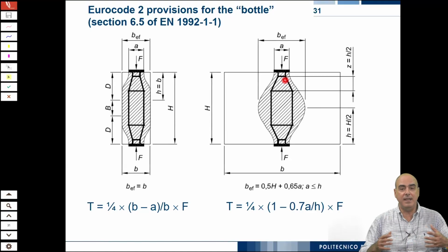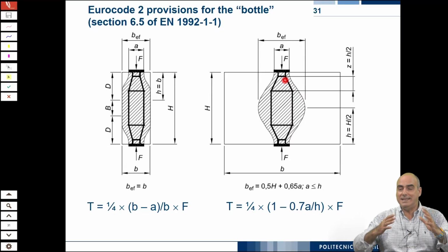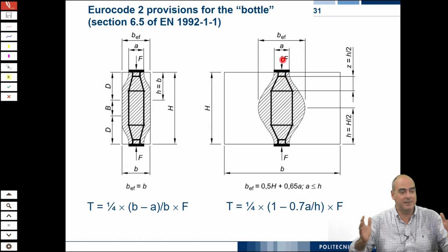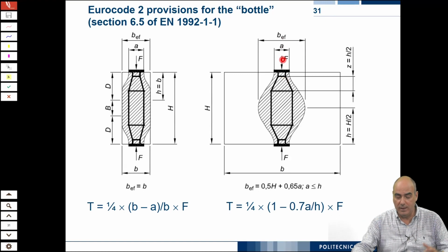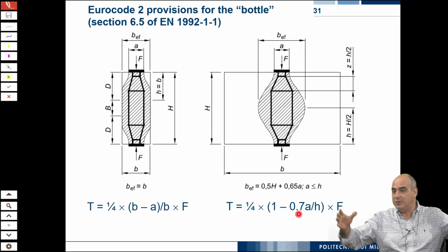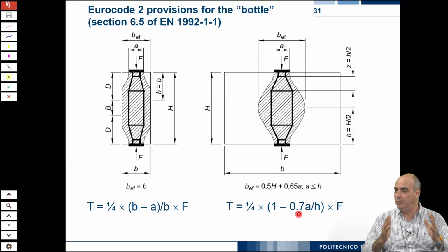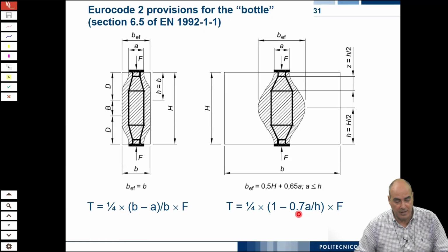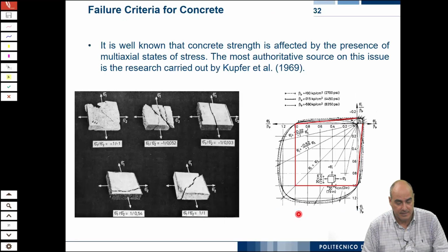Wherever you have a very wide element, what is the area interested by your diffusion? Well, apply the same Saint-Venant principle. You see, you never go wider than a certain collaborating width. But in this case, you see there is a reduction here. Because you can rely on the fact that you have also a lot of bulk material around, which plays a favorable effect. So you do not need the same amount of reinforcement as in the other case.